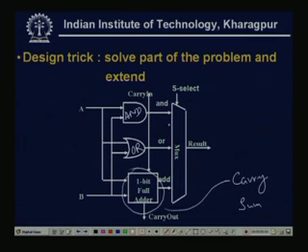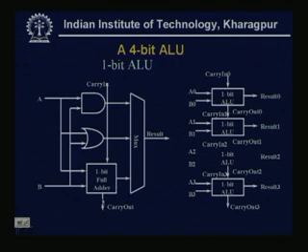It is fed to the AND, OR, ADD, and it is fed to the multiplexers, and depending on the select lines, the particular function will be selected, whether it is arithmetic, or a particular type of logic unit, AND or OR. So, a 1 bit ALU with the logic functions AND and OR and the arithmetic function as a 1 bit full adder can be designed. This is my 1 bit ALU.